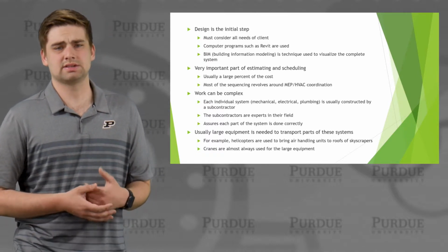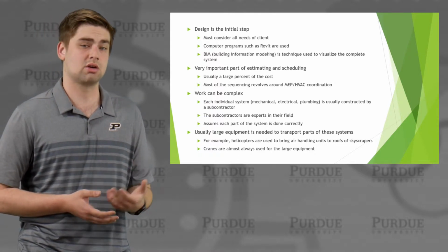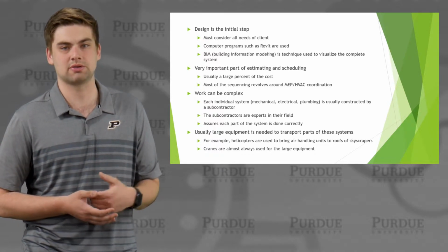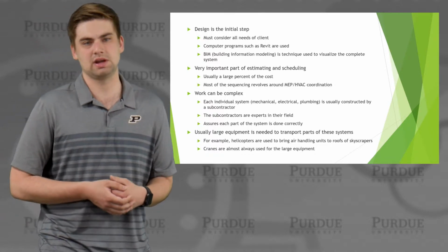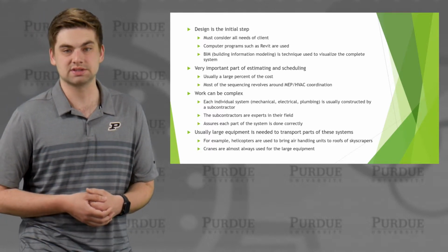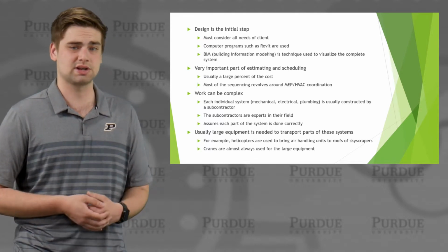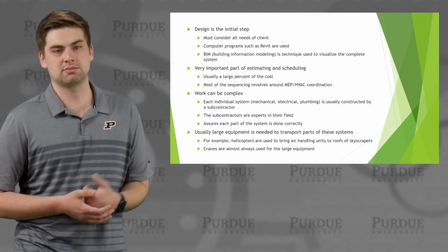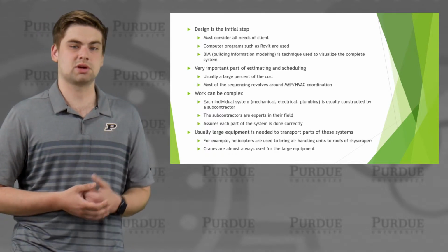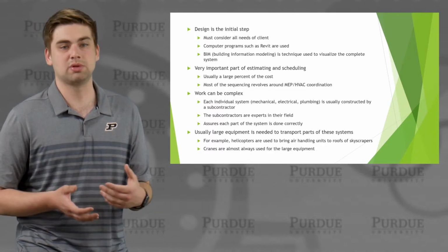This initial step is a very important part of estimating and scheduling. Usually a large percent of the cost is dedicated towards this, and most of the sequencing revolves around coordination for MEP and HVAC systems. Work can be complex, and each individual system is usually constructed by a separate subcontractor, and these subcontractors are experts in their own specific field. This assures that each part of the system is working correctly and is completed correctly as well.